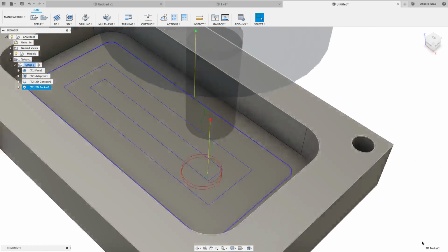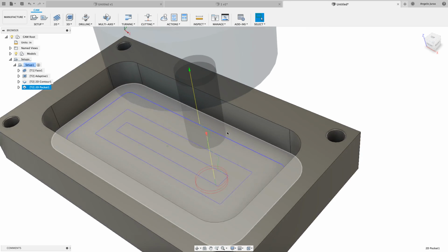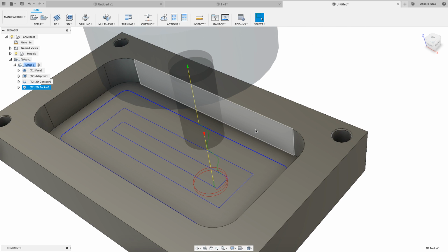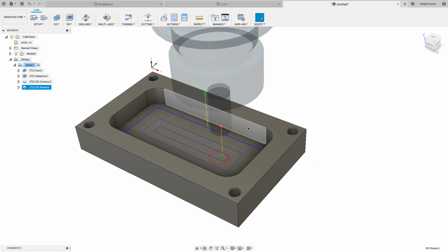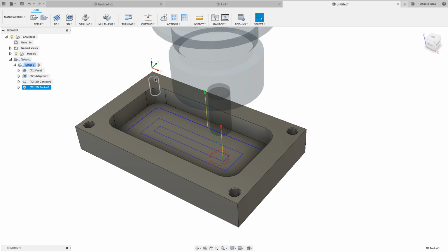All right, so there's our toolpath. So we've faced the part, we've roughed the part, we contour finished around the outside, we did a pocket with the 5/1000 finish pass on the inside. Next thing we're going to do is we need to drill these holes. We need to spot drill it, drill the hole. We need to chamfer around the outside and deburr the part. So you can do it in any order you please. I usually save all the deburring for last.